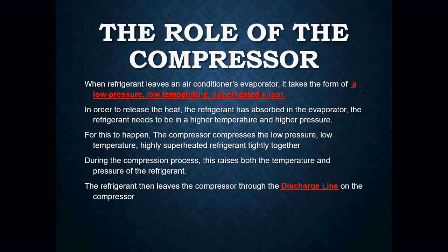It is the compressor that moves the refrigerant throughout the rest of the components. So, let's start at the very beginning. When refrigerant leaves an air conditioner's evaporator, it takes the form of a low pressure, low temperature, superheated vapor.